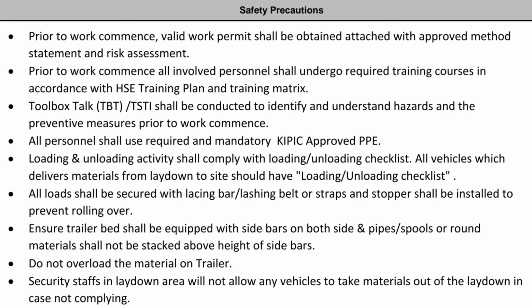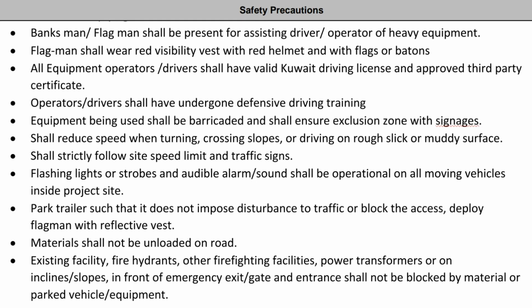Security staff in the laydown area will not allow any vehicles to take materials out of the laydown in case of non-compliance. Banksman, flagman shall be present for assisting the driver. Operators of heavy equipment and flagmen shall wear a red visibility vest with a red helmet and with flags or buttons. All equipment operators and drivers shall have a valid Kuwait driving license and approved third-party certificate. Operators and drivers shall have undergone defensive driving training.